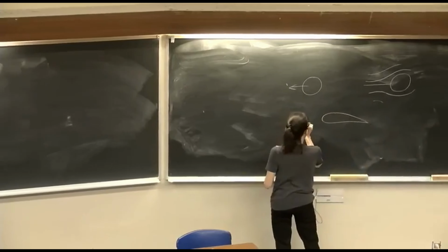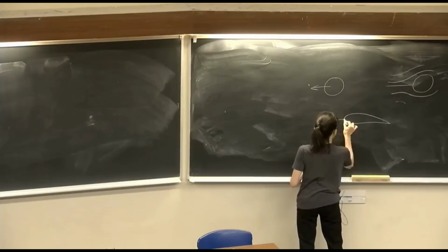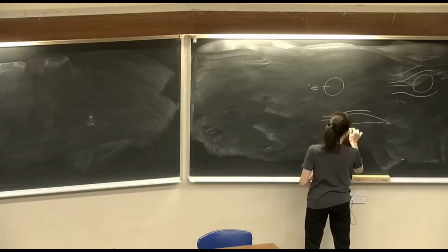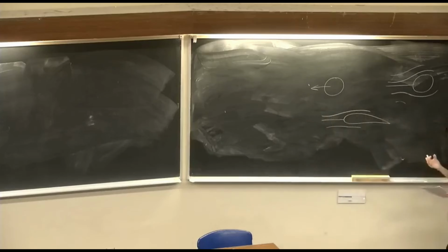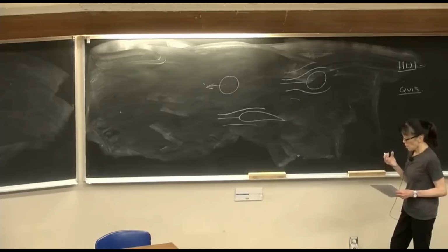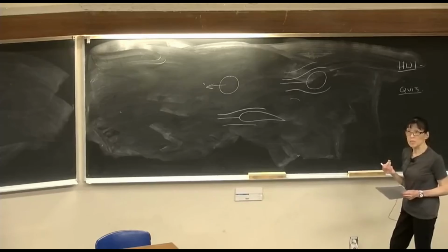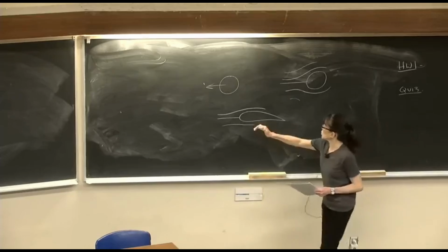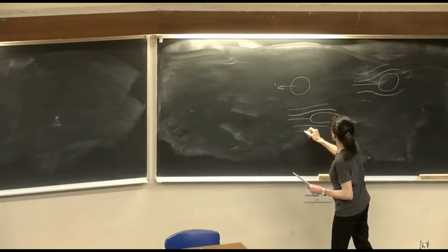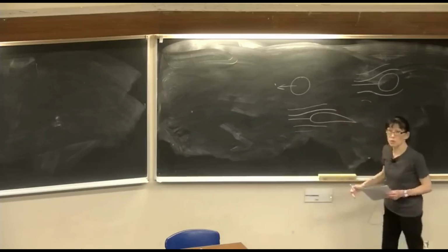If I indicate the direction of the flow, I might do something like this. We'll go over, I think it's in Chapter 3, how fluid motion is represented. This could be something referred to as streamlines, which are lines everywhere tangent to the velocity, so they do indicate the direction of the flow.